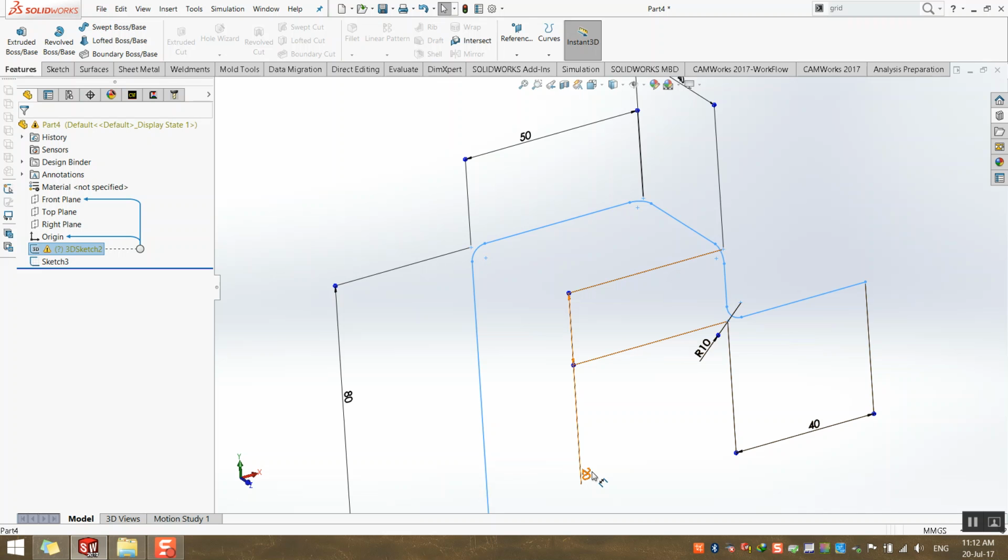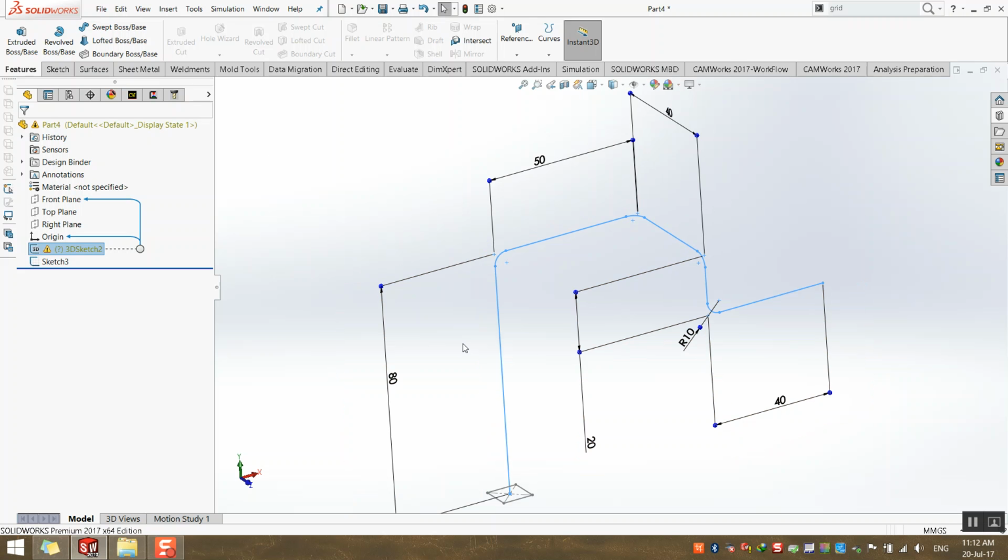To do fillet, let's say you are piping. You can draw it with fillet, or you can draw it part by part. You can draw the straight pipe separate and the elbow separate and the T separate. There is something called weldment, another module called weldment. If you do structure pipe, you have a special case for cutting at 45 degrees, and if you need a bill of material and cutting list and standard tools, the table is automatically generated. We will see. We will go to this module.